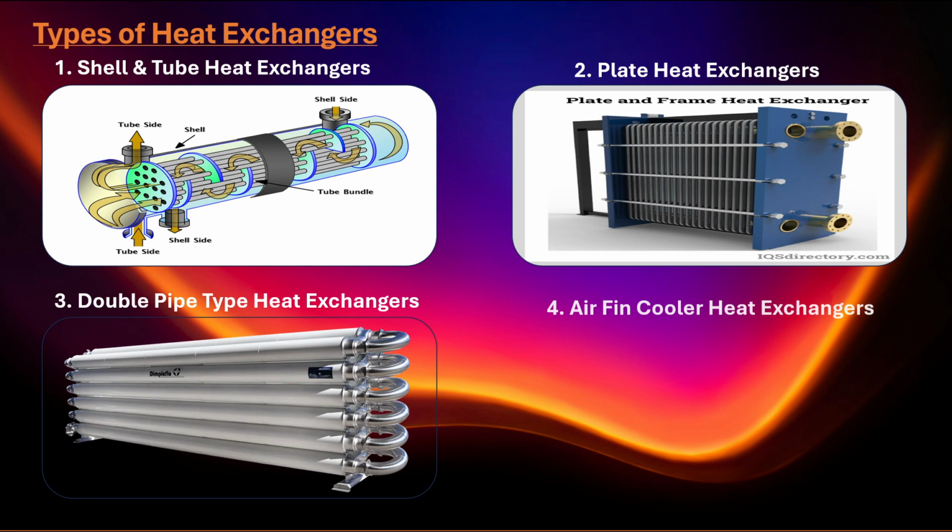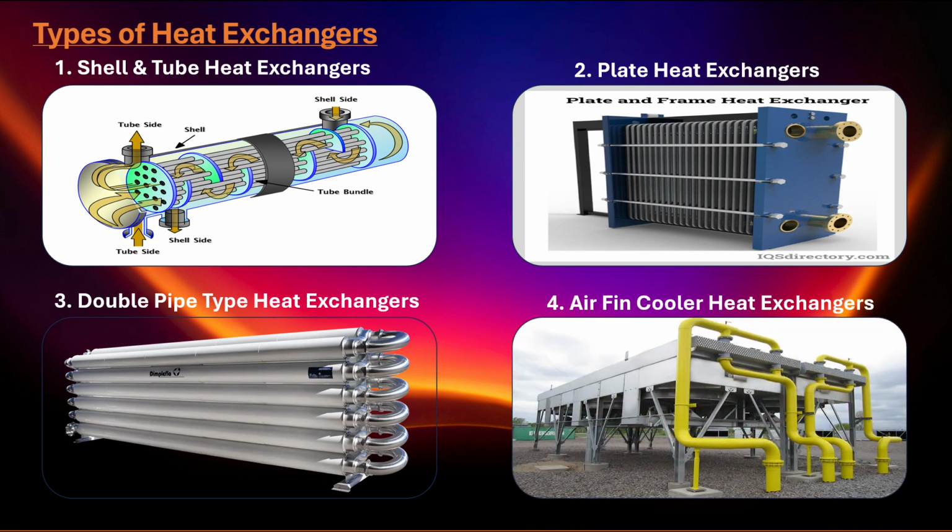Fourth one here we have is an air-fin cooler heat exchanger. It uses ambient air to cool process fluids, eliminating the need for cooling water. The fan cools the fluid flowing through the tubes either based on the induced cooling or forced cooling method. They are common in petrochemical plants and the power generation industry, where water is available in scarcity.